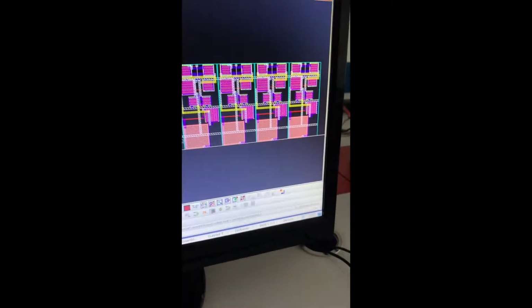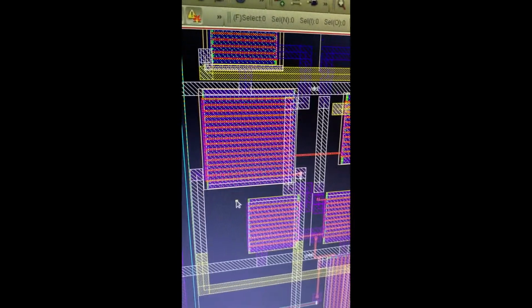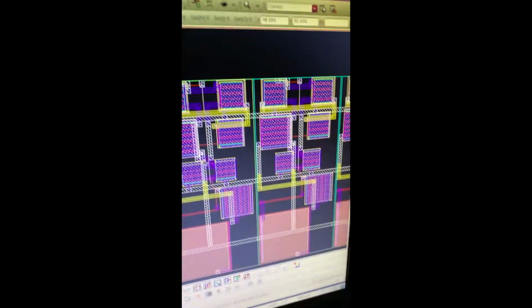There's the VDD, ground, and bias lines, as you can see, going through. And when you look closer, these are the transistors. They have multiple gates, and because W/L ratios of them are so big, there are multiple gates of these transistors, and they look like this. There are 4 transistors, as I said, and in order to save space in the chip design, there's only 1 bias circuit that drives all of these